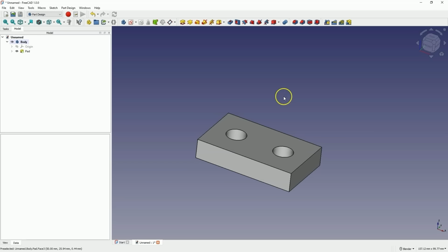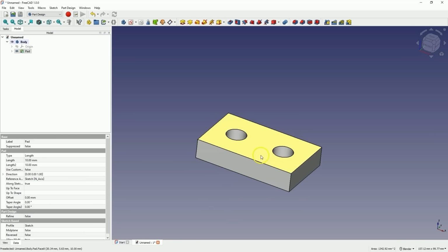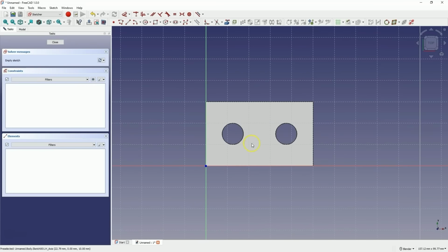When it comes to 2D sketches, we can create sketches on the basic planes of the coordinate system. Just like in the case of the sketch we used to create this solid, we created this sketch on the XY plane, and this is one of the three basic planes of the coordinate system. We can also create these sketches on the faces of the solid. To do this, we simply select the model face, that is, left click on this face and choose to create a sketch. And now this model face is the sketch plane, and we can create a sketch on this face.